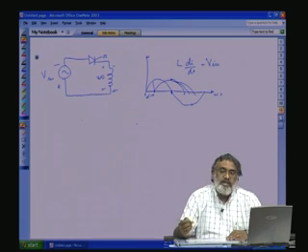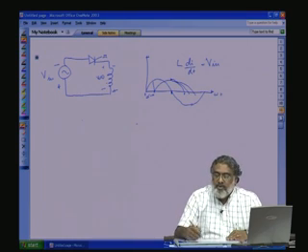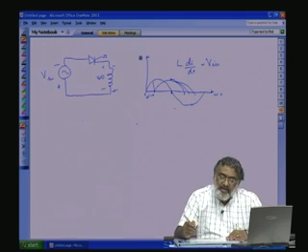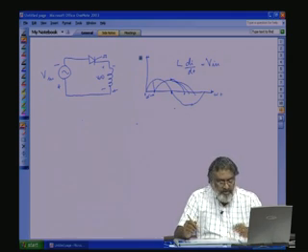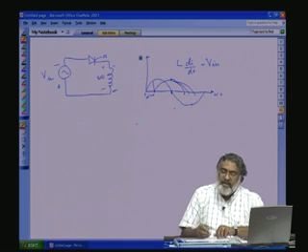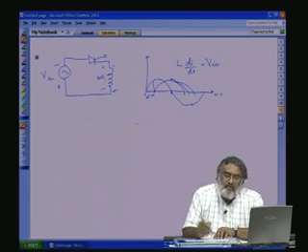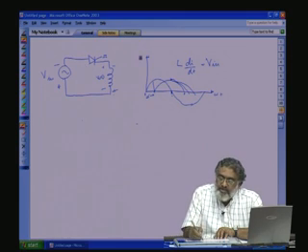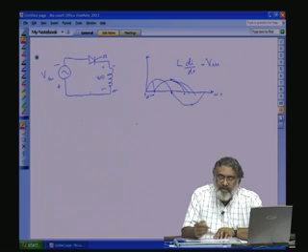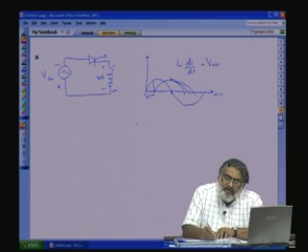At the same time, there is another requirement. Current cannot stop instantaneously in the inductor. Current cannot abruptly change. So we should provide another path for this inductor. There, the concept of freewheeling comes. What it means, when this voltage becomes positive here, that is during this portion, if we want the thyristor to switch off from this point onwards, at the same time we want to give an alternate freewheeling path across the inductance. What we can do, we can provide a diode here.